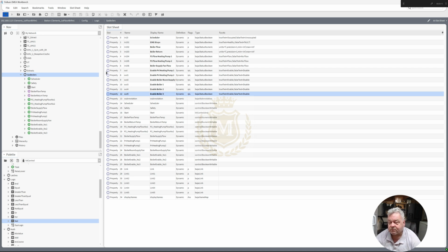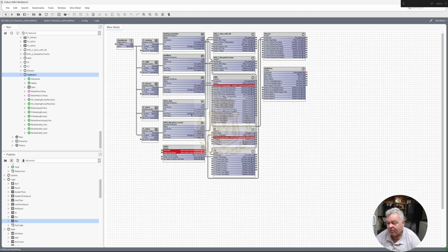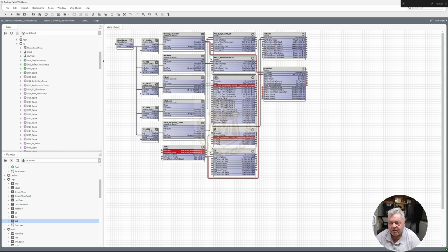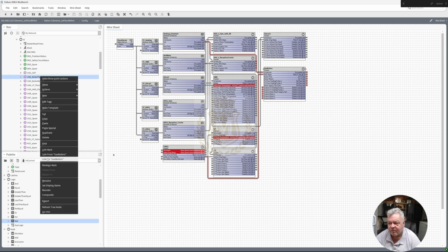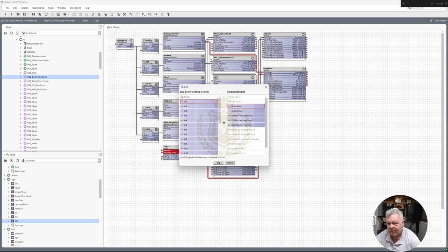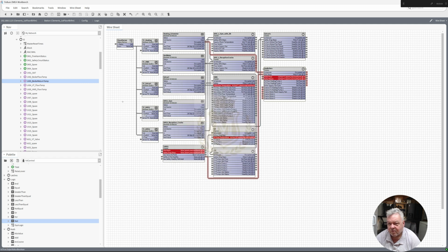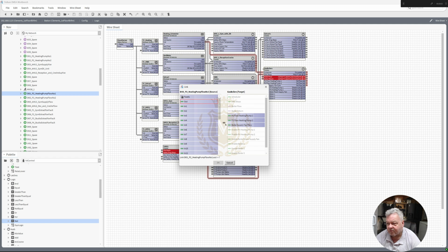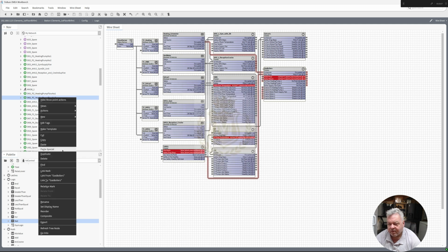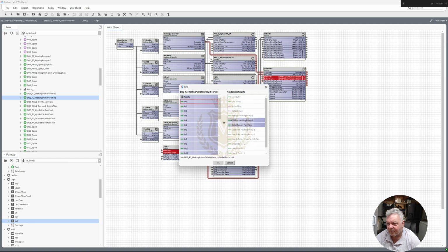Right, so now we will link mark this block once I've just put in the heating scheduler, the emergency stops, link mark, and then let's look at this IO. Boiler flow, link 2, out, boiler flow, boiler return, link 2, out, boiler return. Then we've got heating pump 1 flow, link 2, out there, link 2, out there.